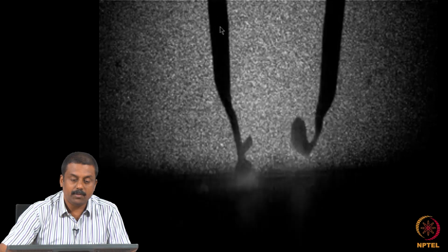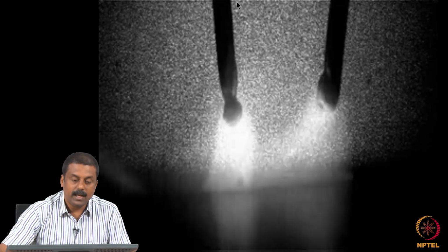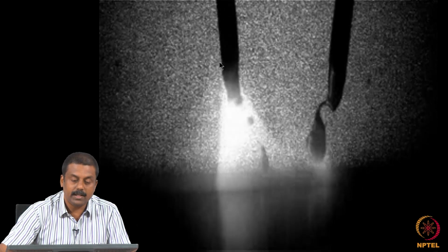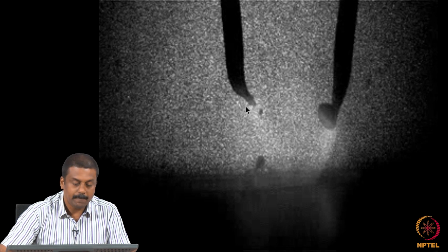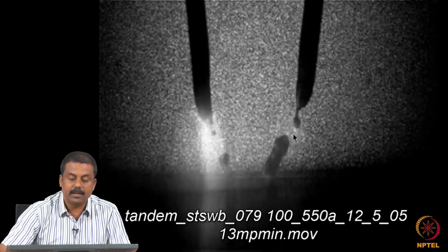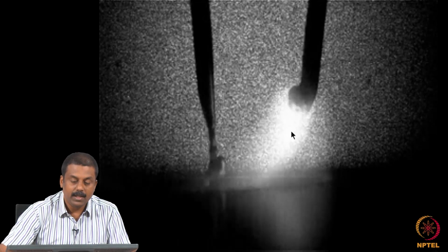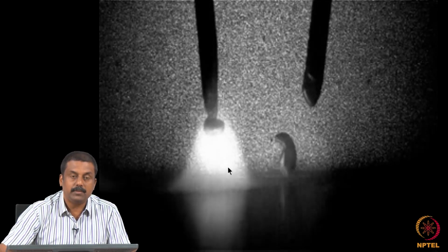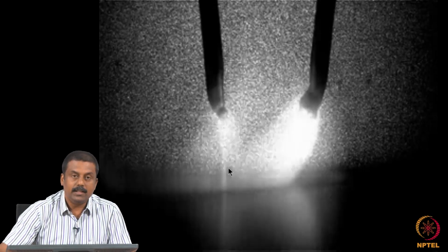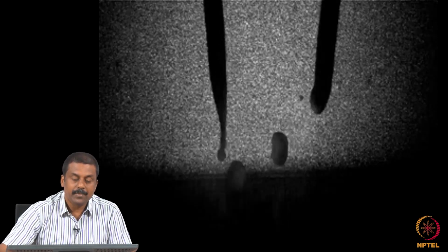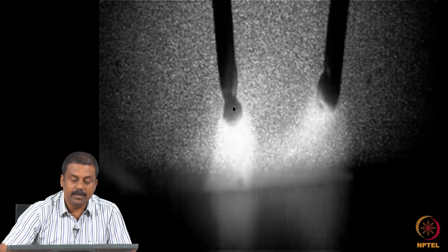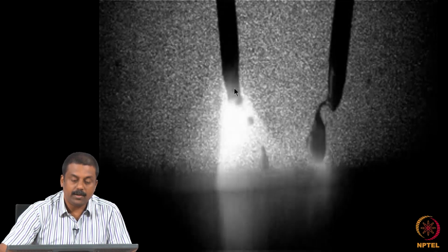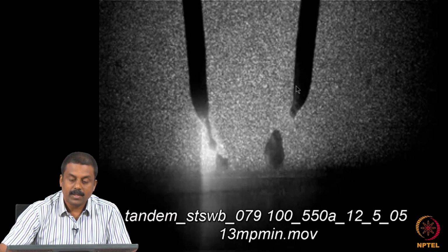What you see over here is one filler wire and another filler wire, and we are passing varying amounts of current. Based on the current, we may either transfer droplets in a spray mode, or in this case as globules in a rippled mode. The characteristic of metal transfer is very critical, as we explained in laser welding, where the keyhole is important for stability. In this case, the transfer characteristic of the droplet is extremely important, and you can already see here that the molten droplets are sprayed towards the workpiece.